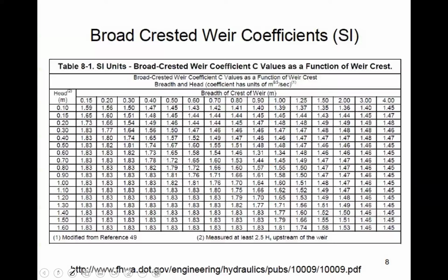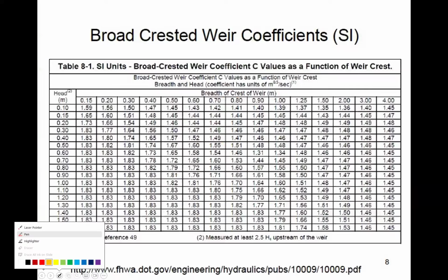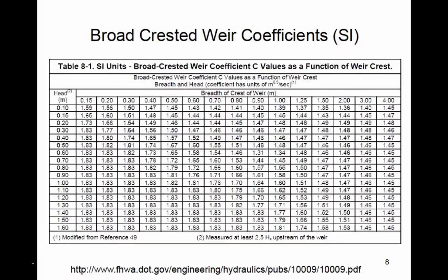Remember, I'm gonna continue to the next slide here. Now, one of the other things that we talked about was that coefficient that we have in the weir discharge equation. I'm going to write it up here. Discharge was equal to C times width times H raised to 1.5. As I said, that C value, you can't really theoretically estimate it, because the assumptions we made, velocity and head loss and so on, are not really easy to theoretically estimate.